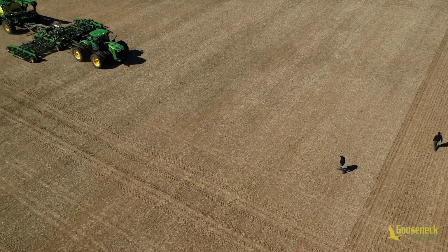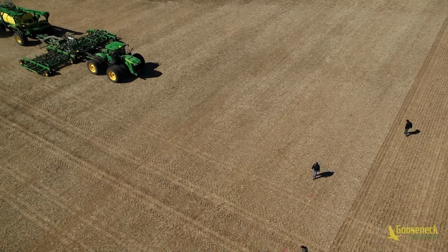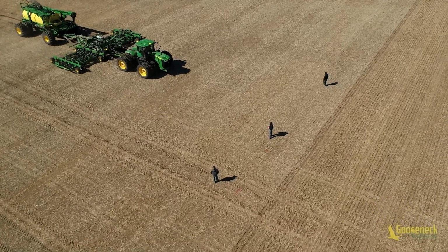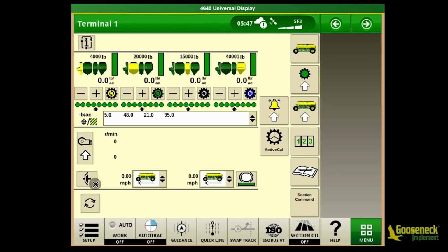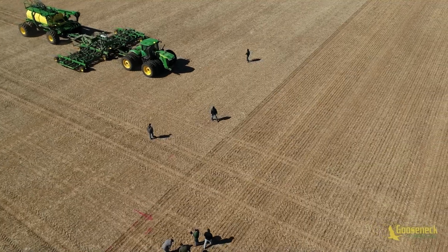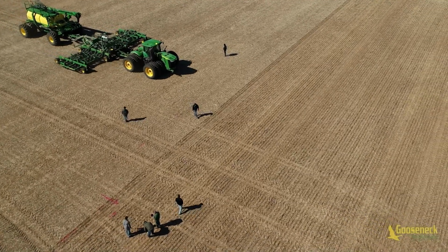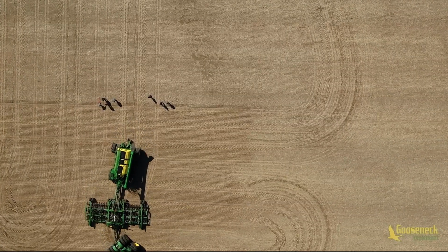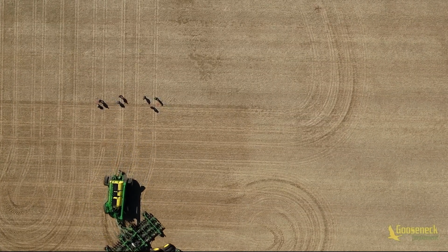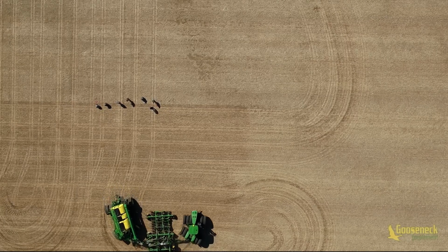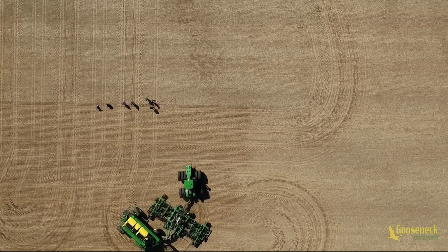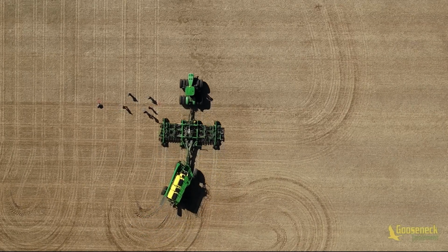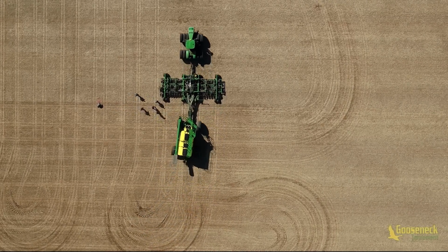After the headland passes are made, we will then enter the headland perpendicular with our discs up. Using the master switch on the display, we will activate the main drive. Blowing seed on top of the ground allows us to do an accurate measurement of our skip or overlap. The operator must maintain consistent drive speed while entering the headland. Perform a U-turn and then exit the headland at a consistent speed to then measure our skip or overlap while exiting the headland.